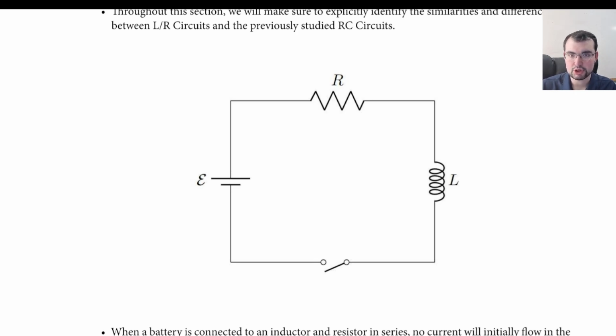So the inductor pushes really hard back at the battery. It says, okay, don't change the current that quickly. So the battery responds, okay, I'll lower the change. Then the inductor is less unhappy, so it sends back a little less push. So it's still lowering that rate, it sends a little lower push, and so on and so on, until eventually you've sort of tricked the inductor into changing the current through it by going slow enough.